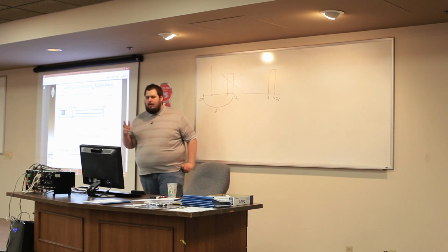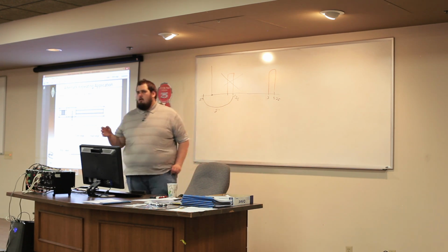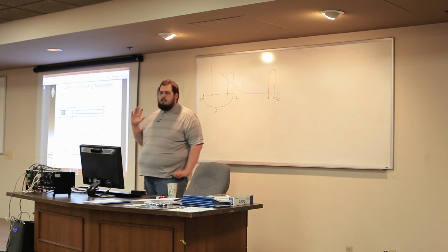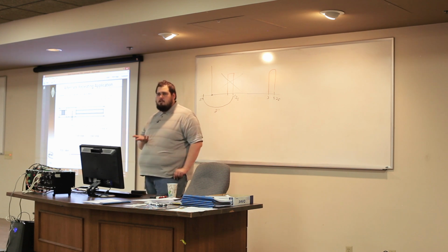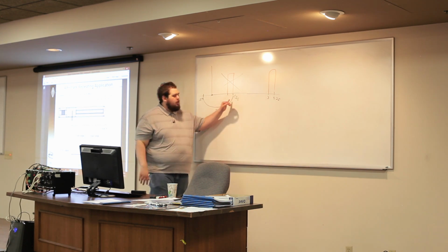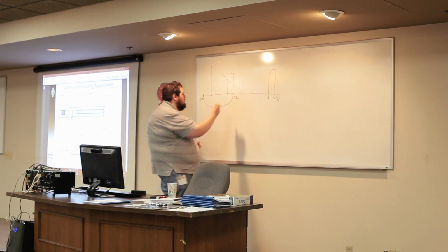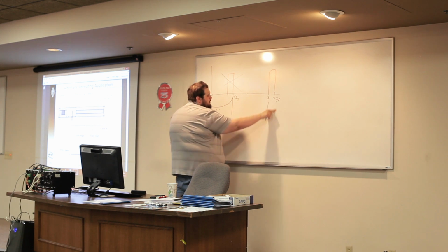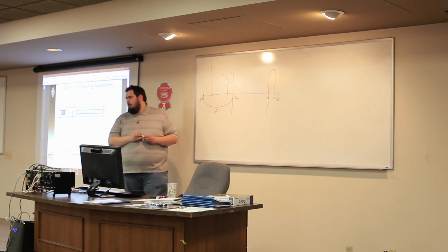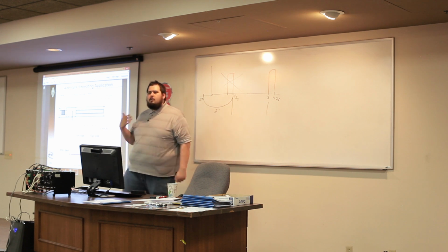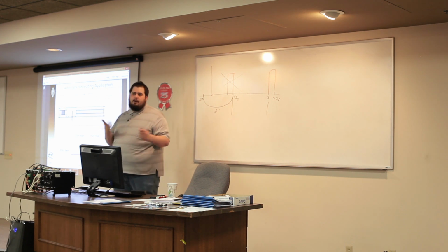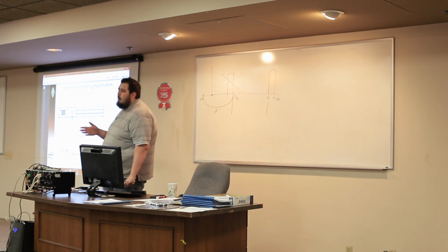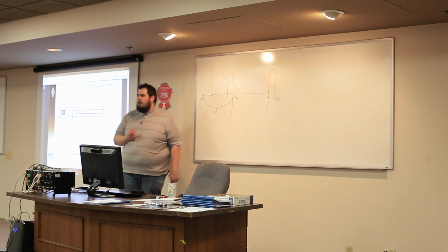But in order to handle this, there's a couple of different approaches you can take. One of them, which is how you would have had to do it in Turbo, is to basically have a PLC or something else that watches the motor position, and as soon as it determines that you're inside of that range, from here to here, or from here to here I guess I should say, you have that PLC set up the position compare stuff for you. That way you're always in between your comp A and your comp B registers. You just don't set it up until you are in between them. But for Power PMAC, we've added in a new functionality.